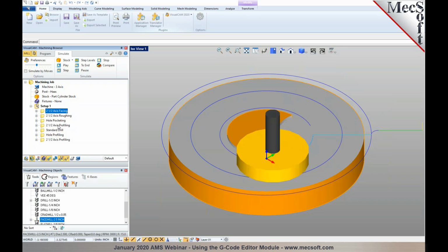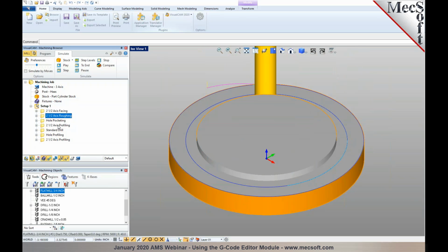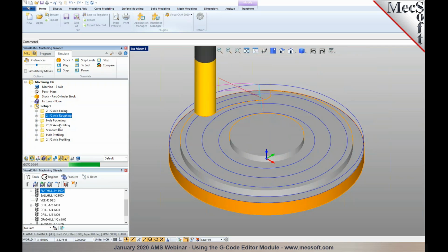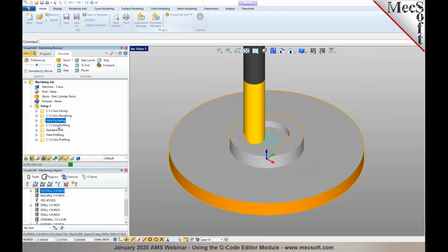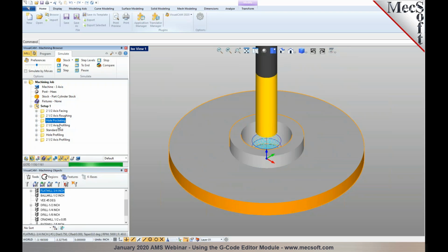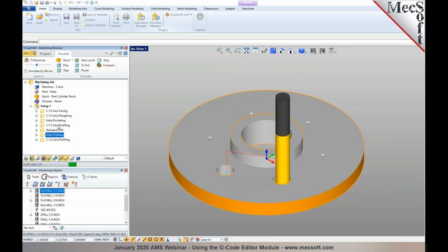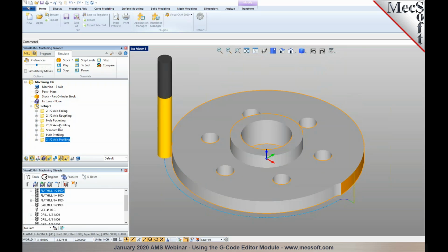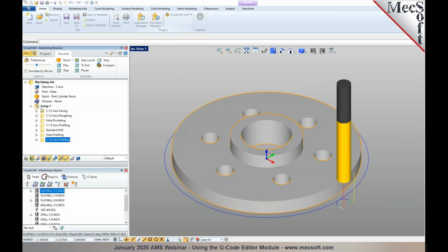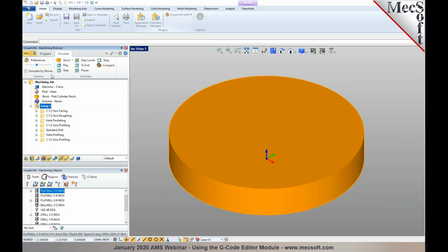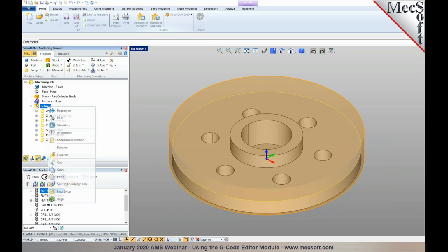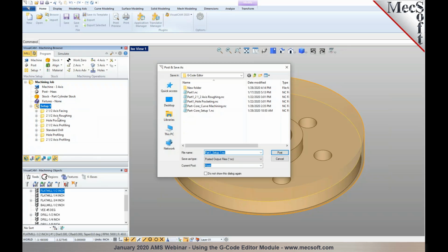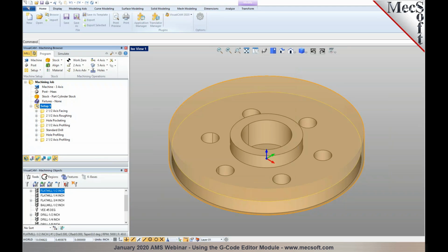And the simulation, the cut material simulation that you're noticing here is based off your programmed toolpaths. Now, once your toolpaths have been programmed and simulated, you would be post-processing these to your CNC machine tool controller. When you post-process these, you may have defined several additional parameters in your post-processor, depending on whatever post-processor you're working with. So the post-processing adds additional information, and you might be using different formats for arcs or helical interpolations and all of those. So in this particular step, I'm going to go ahead and post-process.